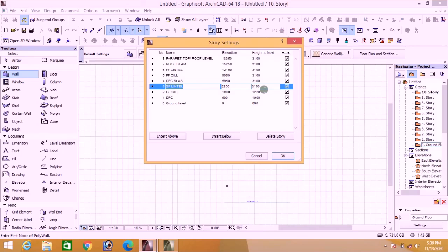Now, when you have 750, then you are going to create your decking beam. Decking beam of, let's say, 250, then 250 with the deck slab. You add them up together. You do your mathematical arrangement here. Thickness of the slab is 150. The decking beam is 250. 150 plus 250 gives you 400. Is that understood? 150 plus 250 gives you 400. Now, this 400 will be sitting on top of your 750. So 400 plus 750 will be giving you 1150. So we'll have 1150 on top of our lintel to bring us to the decking top.